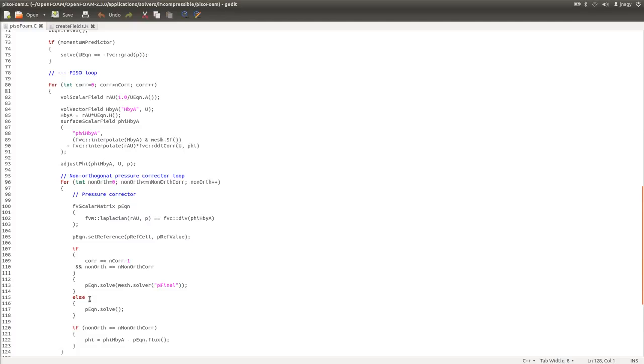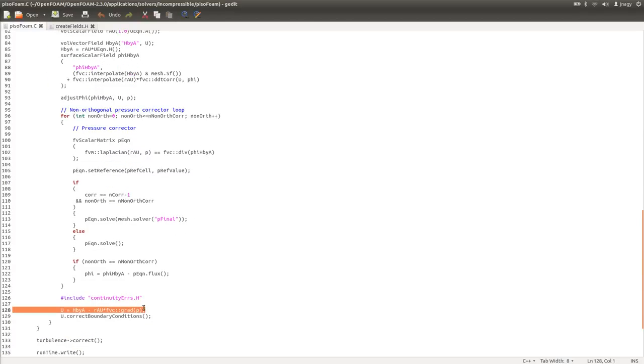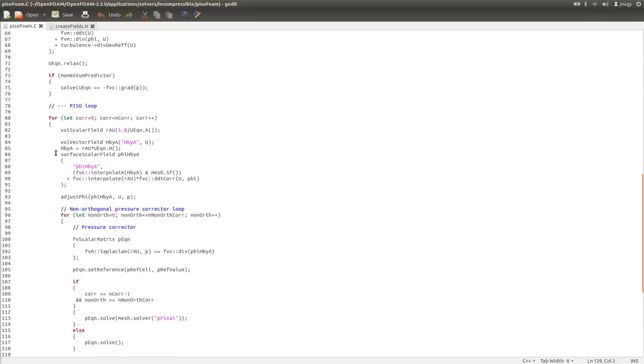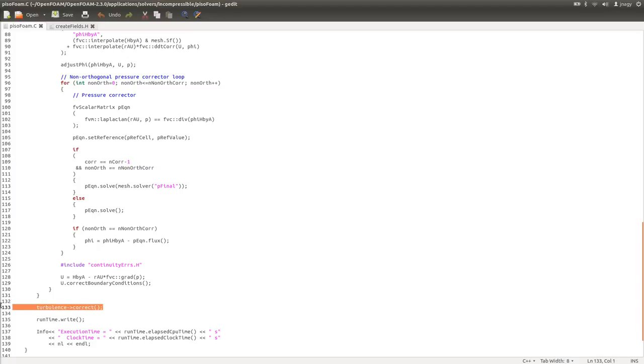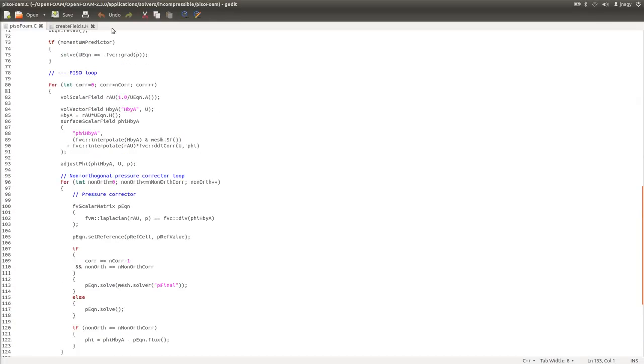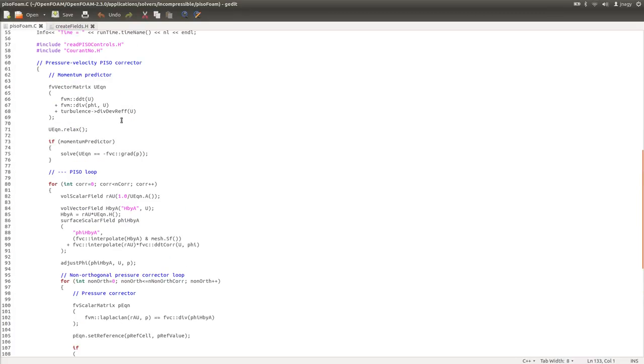So then we again solve the pressure equation a couple of times, and then we are updating the velocity. And if we say that we did enough outer loops, then we calculate the turbulent values, and then we go to the next time step. Okay, this is what the source code looks like, and as you see, turbulence enters at this point, and this div-def-ref is very similar to the div-def-ref term in SimpleFoam. So I will not talk about the turbulence models. You can check them in SRC turbulence models if you want.